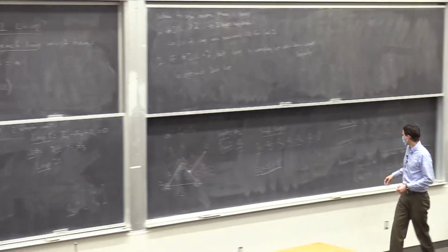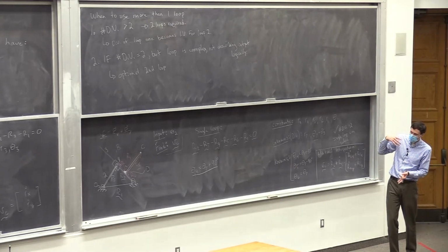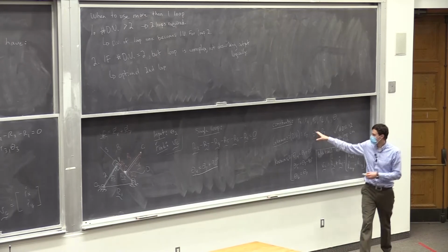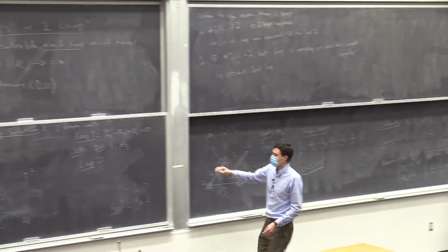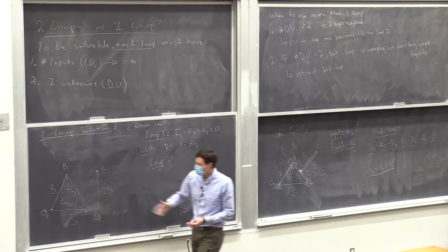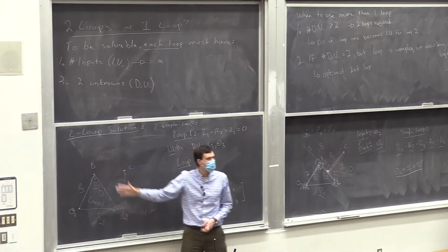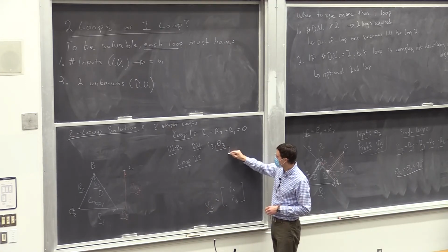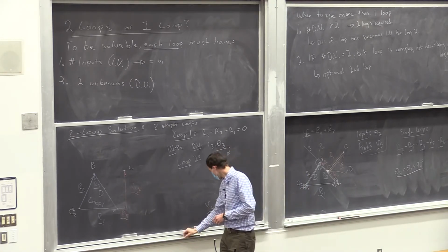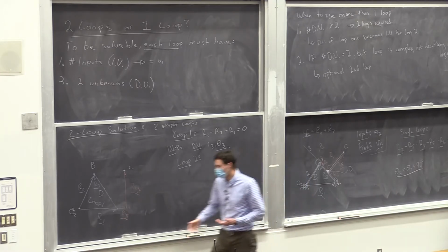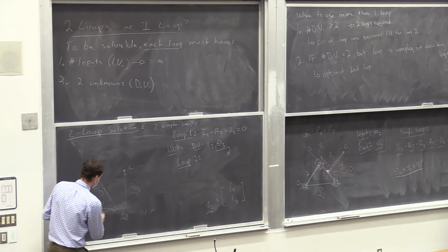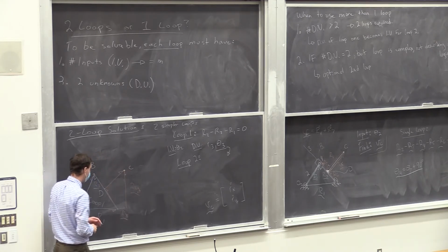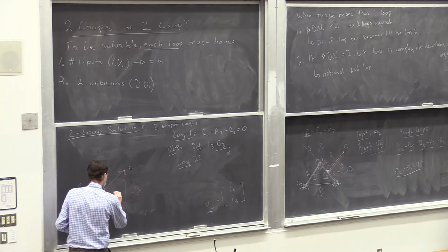And remember our last example, we had an output of the first loop became the input to the second loop. So we can look at these, like these were from last time. This time our outputs are R3 and theta 3. So let's use this theta 3, angle of link 3, as the input to our second loop. So we output it from our first loop, and it's going to come down to our second loop. And we really just want to capture the angle of it. So let me just design a simplest vector out along that. So 3.